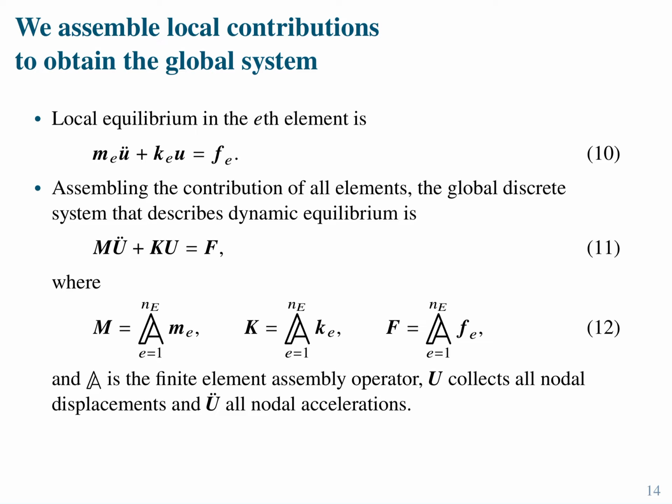And we call it like that, right? So what is it? It's not that fancy. We just have to sum things at the right locations in the matrix. That's all it means. That means that if elements 1 and 2 are connected, I need to make sure that element 1 contributes to this degree of freedom that is shared, and element 2 also contributes to that degree of freedom that is shared, right? This is very straightforward. Everybody who has done any finite elements knows this.